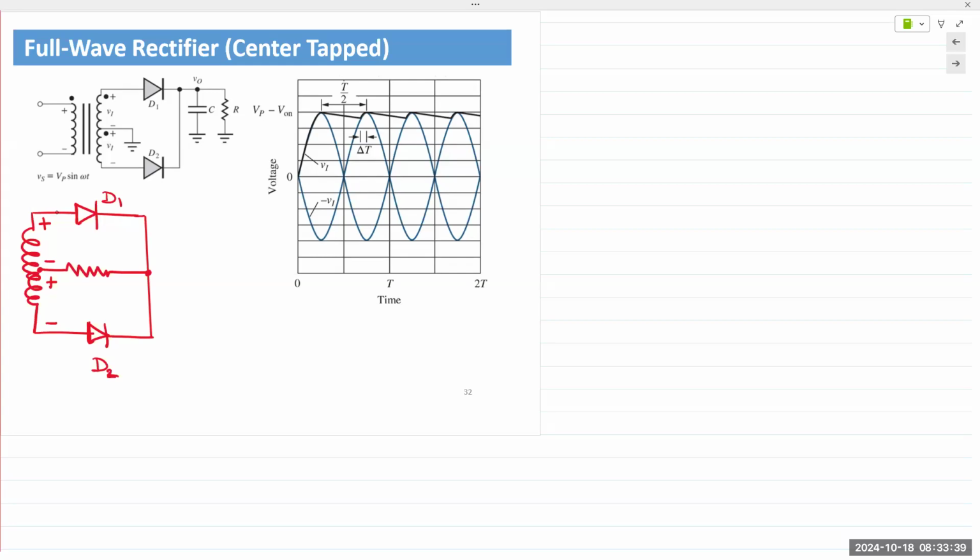But if you wish to, let's say, as I said, the variable power supply that I used to have, the primary input was 220 volts, and then the output was 15, 12, 9, 6, 4.5, and then 3, and then 1.5. So depending on what output voltage you want, the number of turns would be different.